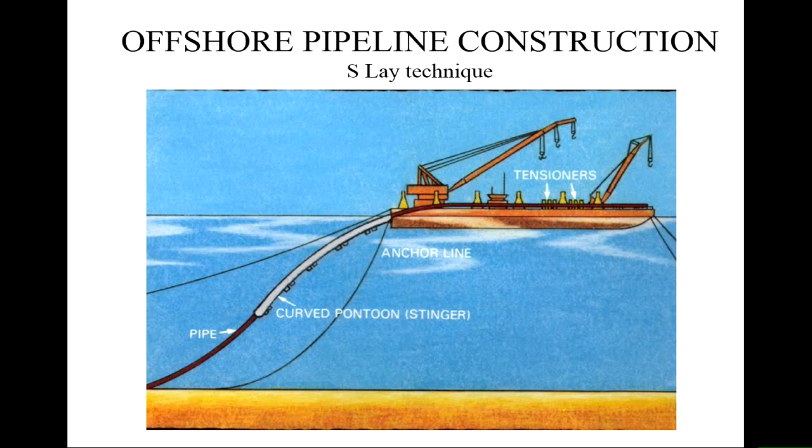So, how is it cooled? When you finish welding, is it cooled in the stinger or? Just in air. There's no forced cooling in these cases because that can make martensite formation more likely. So you don't control the cooling, you allow it to cool in air before you take it to the stinger? Oh yeah, there's lots of things, because it has to be cooled, inspected, repaired, coated before you release it. And so everything happens. It's not just the welding, it's everything happening on that barge. So the barge is like a factory moving along, doing these things.